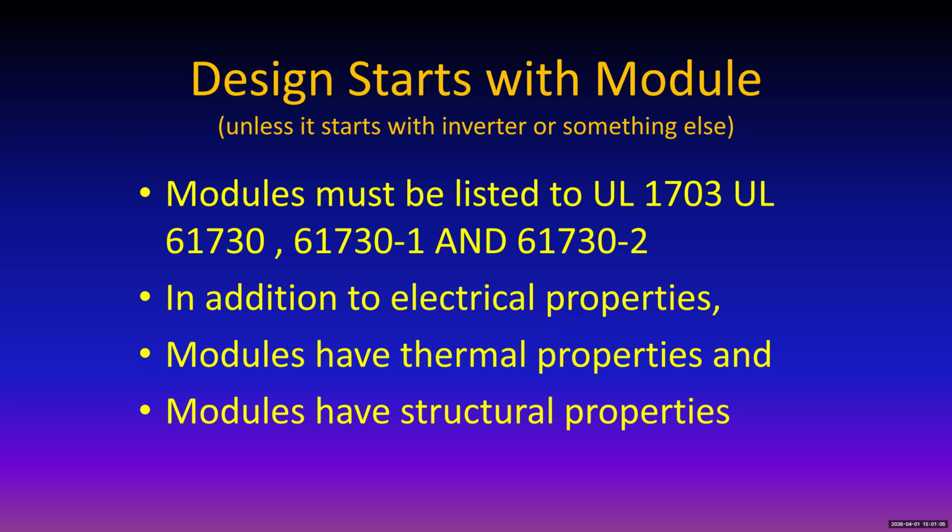Down here, looking at Miami-Dade County, for example, we're looking at 175-mile-an-hour winds. That's a pretty tough mounting system, but it's not an issue because the calculations are very straightforward using ASCE 7-22.